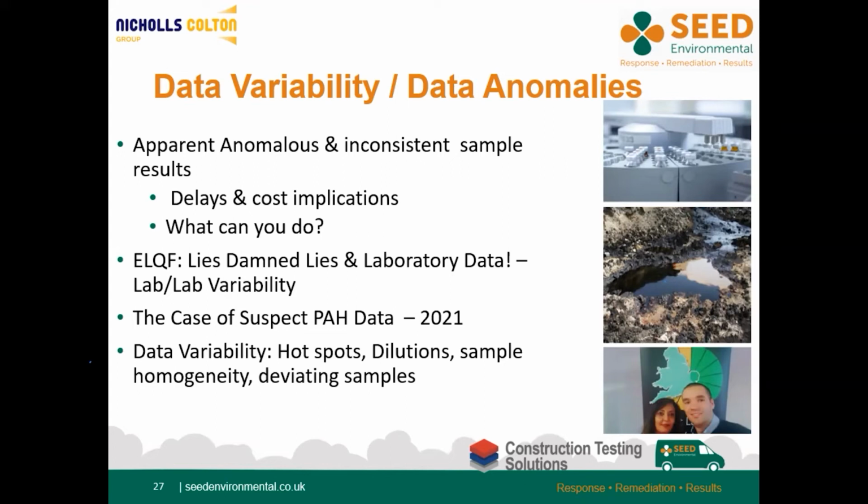I've recently presented with Murray Environmental on a case study where elevated results were seen, and this was due to a small piece of asphalt and sample heterogeneity. Other reasons include the matrix, gravel, clay, which are more difficult to extract from, and also things like dilution errors or lab errors.